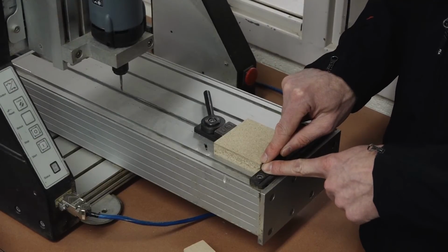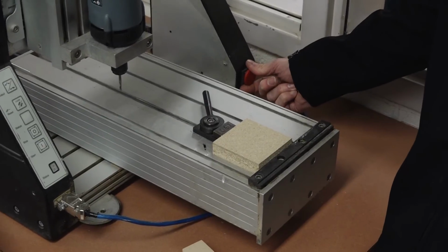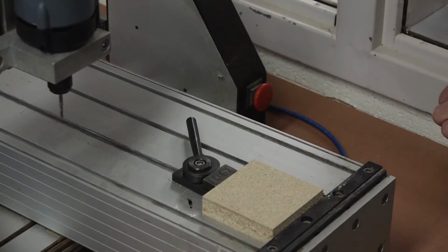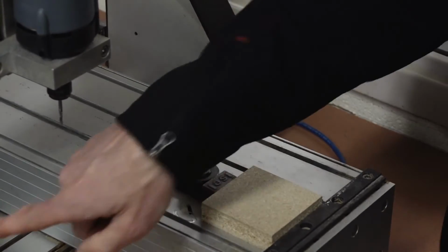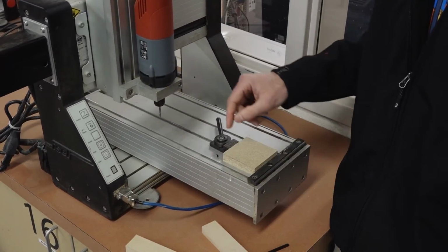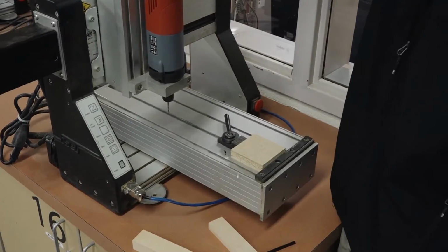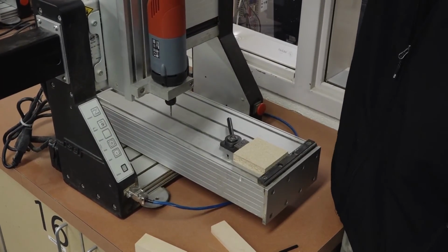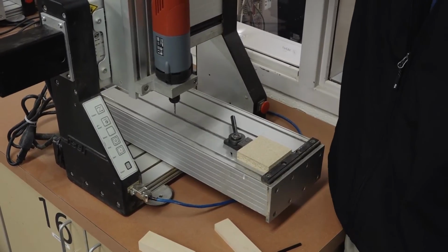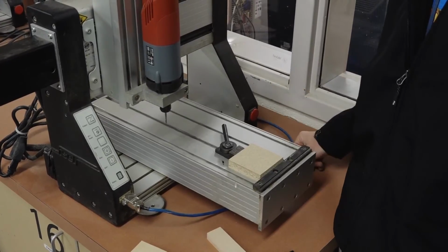So I'm going to use, if I turn this on, and you turn this on by twisting the red and pulling it out, and if the power were on in here, the red light would come on and it would count down to zeros, and I'll show you that in a second. And then you could use these handles to turn it, but the problem with using these handles on the servos when the power's on is the power is engaging the servos and it's harder to turn. So generally you keep the machine off.